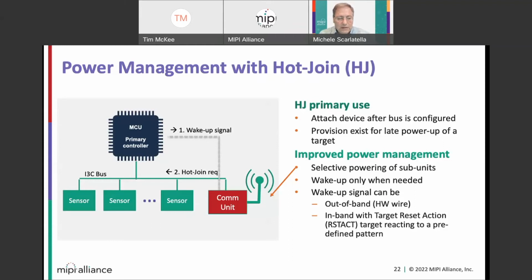In that sense, I3C does not have a specific feature there, so this has to be designed at the system level. It can be an external signal, but as I mentioned, there is one of these hardware patterns, target reset action, that can be used to really issue a hard reset on the communication unit and wake it up.